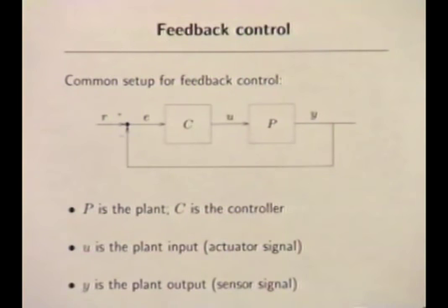Now the problem is, if that were the end of the story, if it were a two-step controller where you measure and then you change the power and hold it there, that's exactly the right thing to do. Here's what happens though. As you reduce the power 1 watt, the plate cools off. And now you say, well, what's the error? There's no error now.